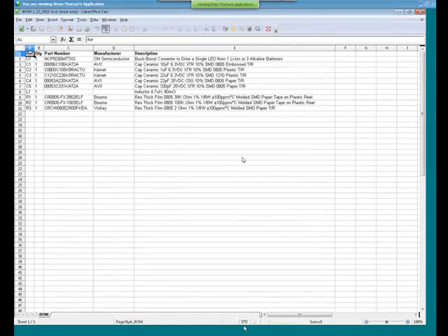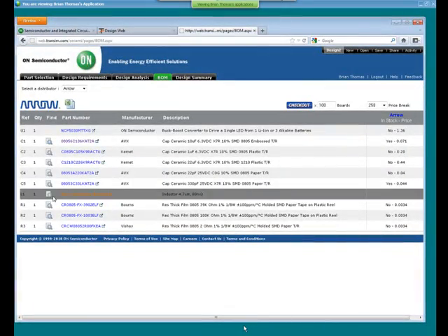And when it pops up, you can see that I can look at my parts in Excel. You'll notice right here on L1 that I'm not having any luck finding this part in Arrow. So if you look here, it's popped up the Excel, and you can see my list of parts that are available here. If I look at this one, you can see that at L1, I don't have a part selected. So I should really go back and look at that and see what I can do to fix that. So I'm going to go back to L1.